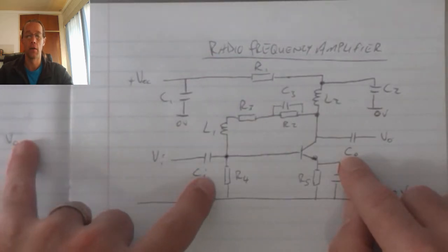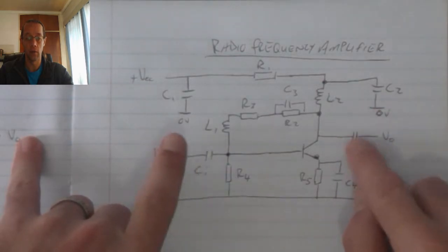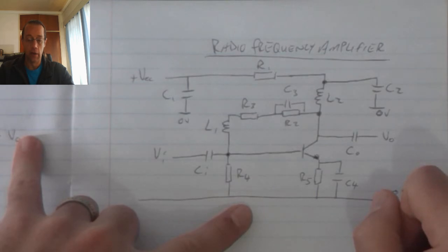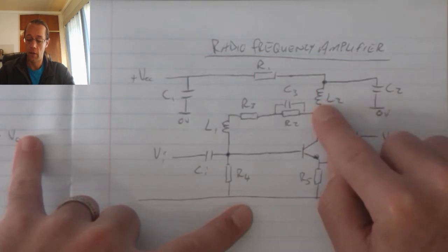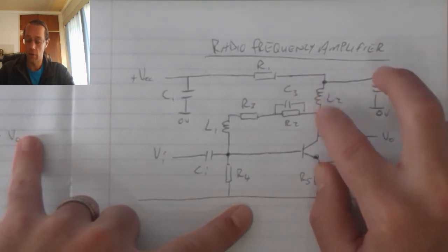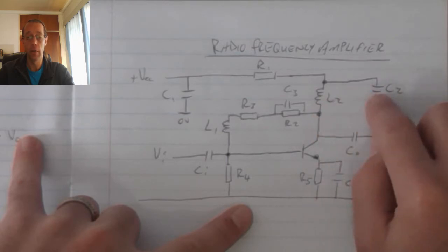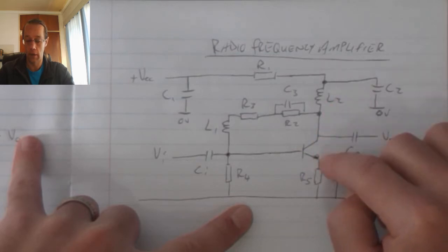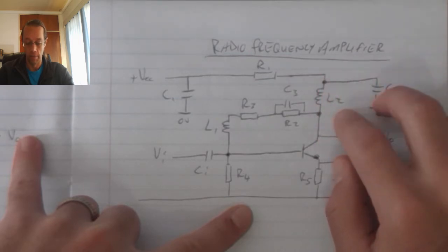Capacitor out and capacitor in are just connecting or coupling capacitors, which blocks DC from entering or leaving the system. How it operates: this capacitor and this inductor will constantly charge and discharge and transfer energy between them. As they transfer the energy between them, they will allow this transistor to switch on and off at that frequency determined by the tank circuit.